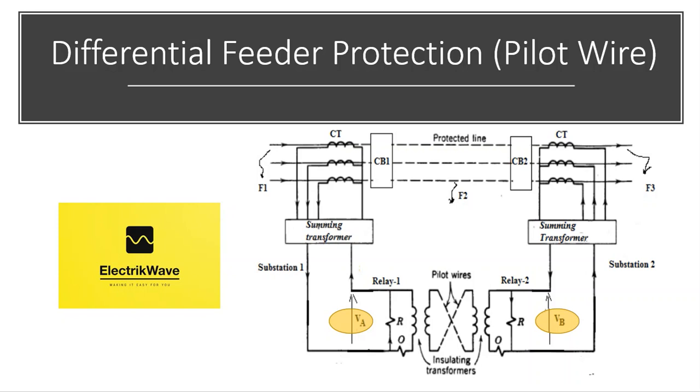To avoid this, health monitoring of pilot wires is required. For this the relay injects current into the pilot wire, and monitors its presence at the remote end. This methodology will vary from manufacturer to manufacturer. Some relays may use high-frequency voltage to monitor status of pilot wires, so the relay operation is blocked, in case of open or short circuit of pilot wire.